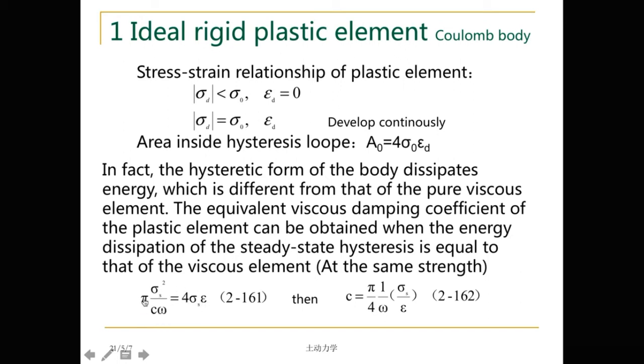That's the same, then we can solve the coefficient C. Viscous coefficient C just equals pi over 4 omega times sigma s over epsilon. Sigma s here means the strength of it, or in the viscous system is the stress amplitude or load amplitude.